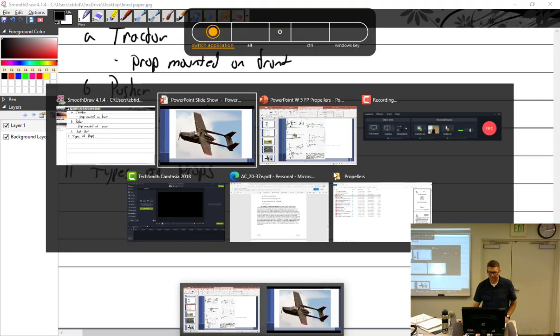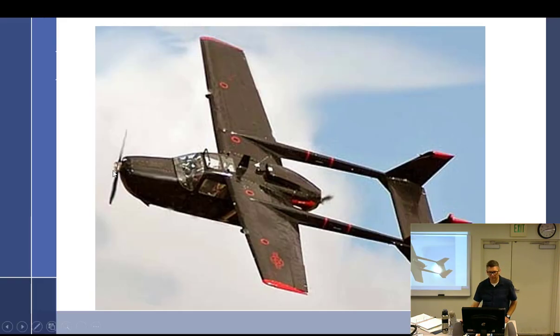Right here, push-pull. This one's pulling, this one's pushing. The Dornier as well. Is it quicker? No, it's a twin engine with symmetrical thrust. So if you lose an engine, you don't have this asymmetrical thrust issue. It's still in line.